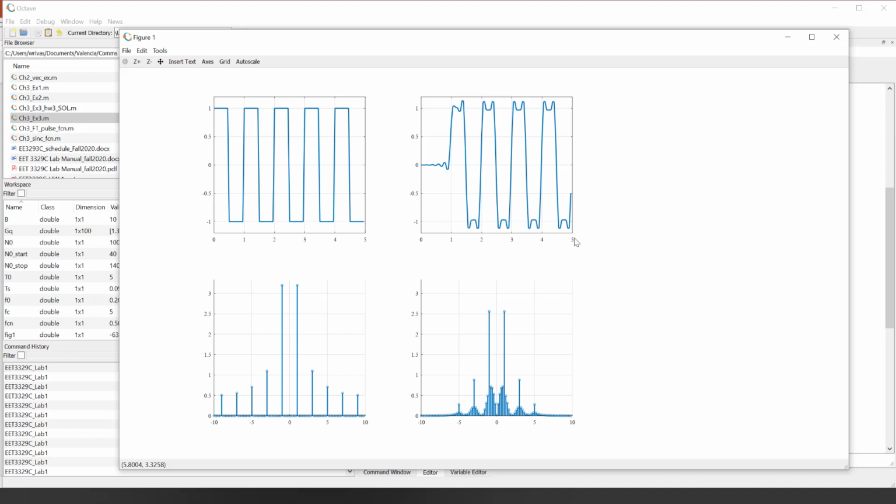Now, if that FIR function is an LTI system, right? The signal should look similar in shape to what I look at the input, and it does, it's similar in shape, right? But we already know that it's going to do a couple of things. One, it's going to create delay because causality imposes that on us. And sure enough, look, the signal at the beginning, there's kind of nothing there.